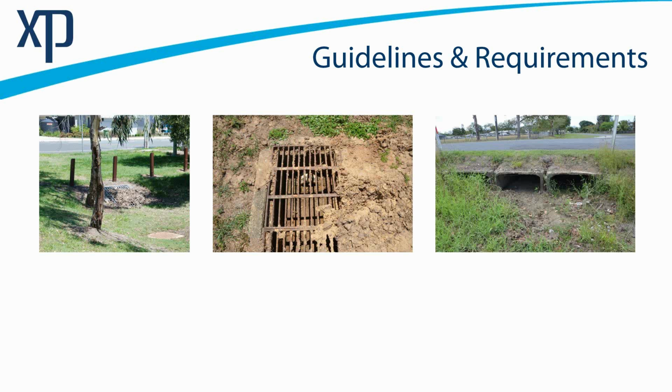In this situation here, asset management guidelines come around this aspect, and this triple set of box culverts has certainly seen better days, with the reinforcing all being fully exposed through decay of the concrete, erosion of the surrounding terrain, and that could eventually lead to a significant issue with respect to that pavement that the culvert in itself is actually trying to protect.